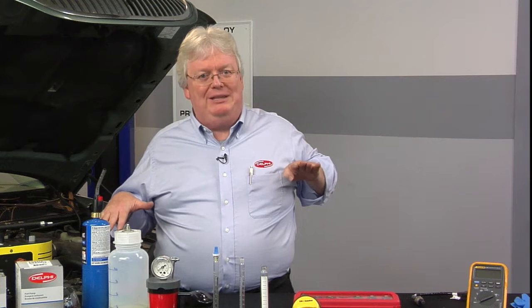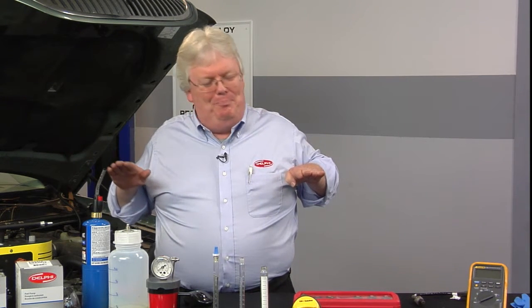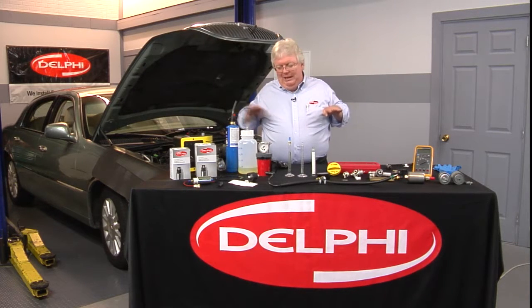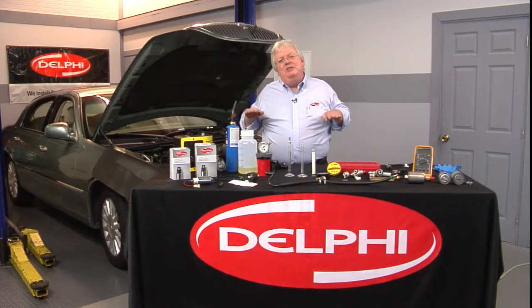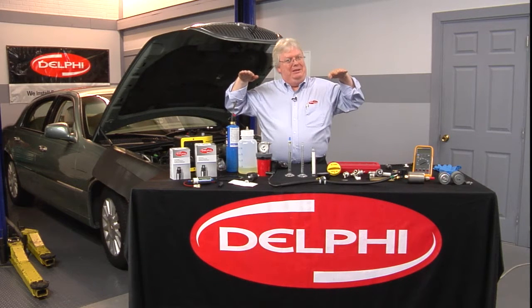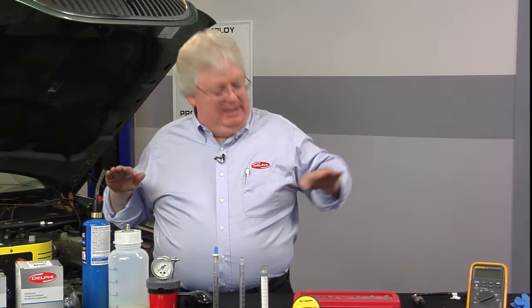At 14.7 to 1, which by the way is also lambda, the perfect 1 lambda, the voltage on some cars and PIDs will go a little higher, from let's say 3.3 to 3.6, as the air fuel ratio goes higher, meaning leaner. So it goes right with the air-fuel ratio, as does lambda.